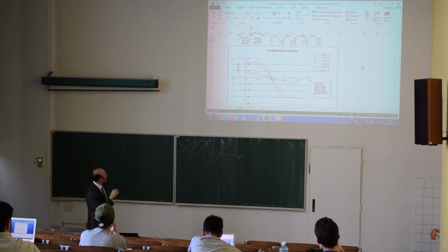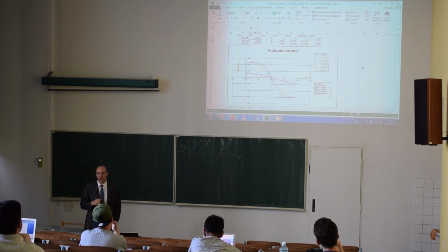So if I had this curve, the 6 here, this hard characteristic, I would have this startup torque. If I would be able to add a resistor into the rotor circuit during startup, I could have a very high startup torque, and then I can switch back to, let's say, 6 ohms, and switch back to this characteristic.